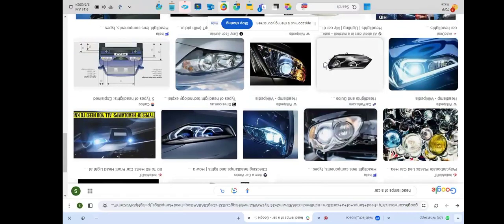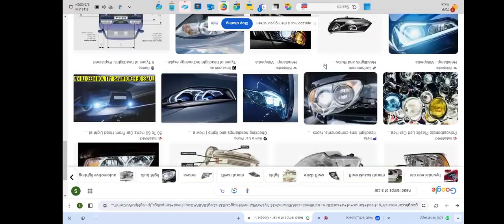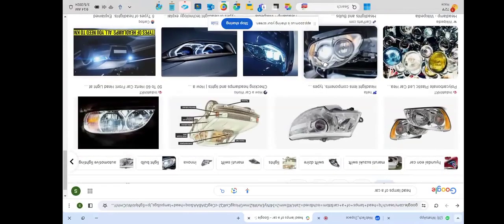For door glass, to go up and down, we can use the motors there. Likewise, there will be loads which can be driven. So which ECU can drive this? The body control module, exactly, correct. The body control module will drive these lights, and the lights will have some voltage and current.